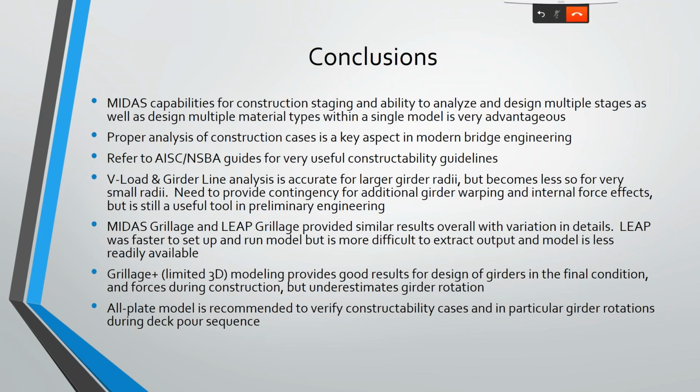The other thing too is doing the temporary shoring model, instead of having a separate, say, LEAP concrete model for the pier cap, and then going into a different one, either STAAD or some other hand calculation, for the steel. Having it all in one, where it can output all of those design results out of a single model, is very, very useful. And proper analysis of construction cases is becoming a key aspect, or it's always been a key aspect of bridge engineering, but we're expected to do a lot more, I feel like, than we have in the past. And so I don't think that's going to get less.